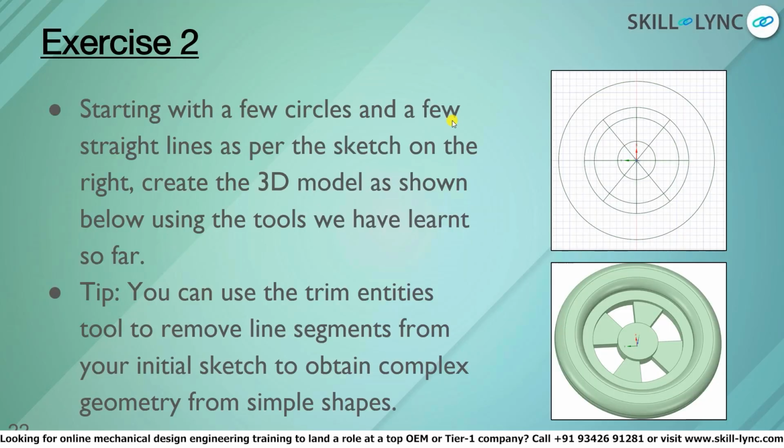Now it's time to move on to the second exercise. In this exercise, I would like you to use a lot of the sketch tools that we have covered in the first week, such as the Trim Entities tool, and I'd like you to use the chamfer, the fillet, the multiple area extrusion that we have covered in this lesson, and the cut option of the pull tool to create a sort of wheel analogy as is portrayed by the bottom image going from the top image geometry.